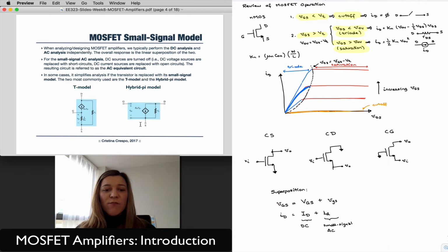And in this case, we have modeled that output resistance, little r(O). You can assume it is infinity, but you can model it if you want to have a more accurate model. That's related to the channel length modulation effect and how, even after you enter saturation, the drain current increases slightly with increases in drain voltage. And it's modeled with a parameter represented by the Greek letter lambda that we have seen has a unit of inverse of volt.